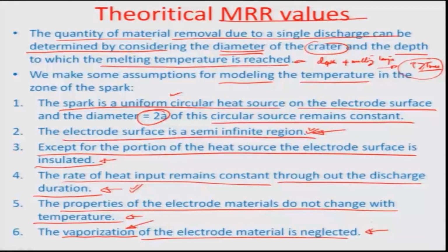Let us now look at the underlying governing equations for solving this radial and Z-based, or depth-based, distribution of the temperature. Let us assume theta to be the temperature of a certain point within the material in degrees Celsius. Let us also assume time t in seconds to be the parameter responsible for the variation of the temperature theta. We also assume a standard K value, the thermal conductivity. As per our assumptions made earlier, we do not assume this conductivity to change with temperature increase, so this can be a constant, in calories per centimeter second degree Celsius.